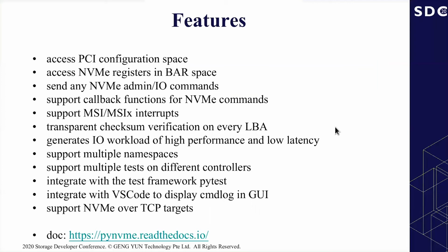Here is a short list of Pynvme features. Pynvme can access PCIe configuration space. It can access NVMe registers in bar space. It can also send any NVMe admin and IO commands. Pynvme supports callback functions for NVMe commands, and it supports MSI and MSIX interrupts.